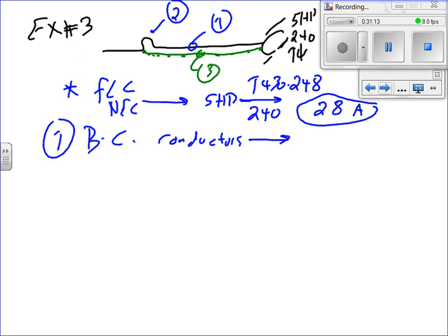So my pump is 240. The system it's fed from is 240, but the actual pump will most likely be rated for 230. Does that make sense? Everybody see the differences? So when I say 240, you go to the table and find the closest voltage to that 240. And if you don't believe me, look at the top of that table, it tells you the range of voltages.